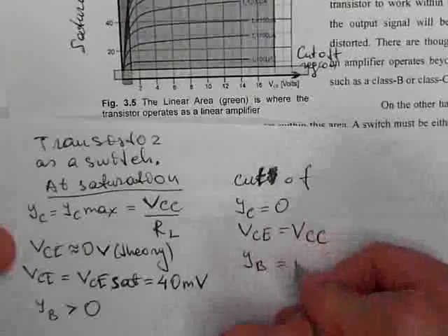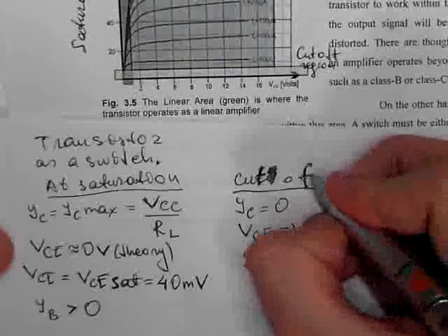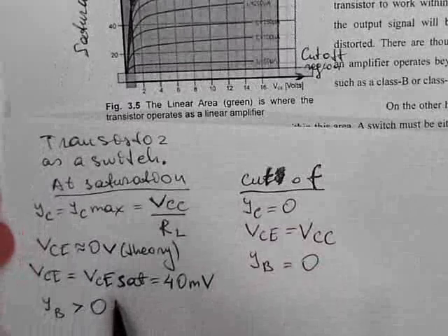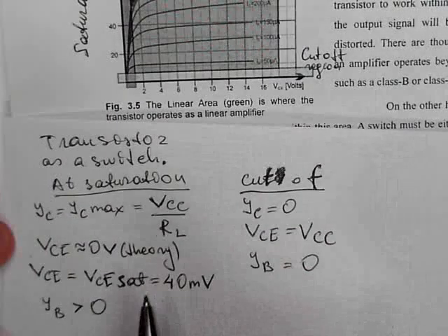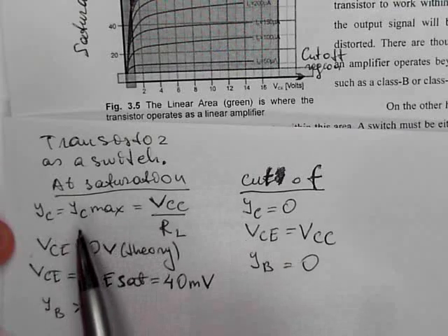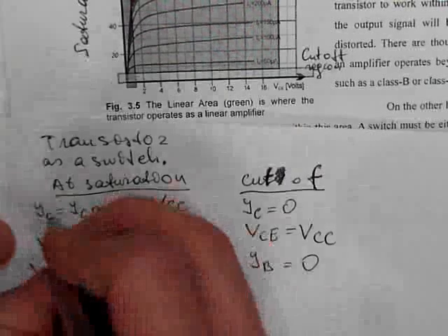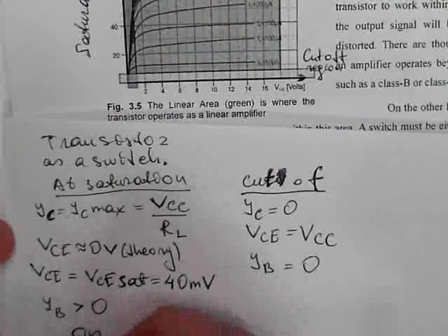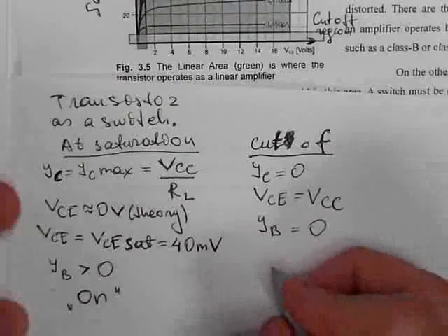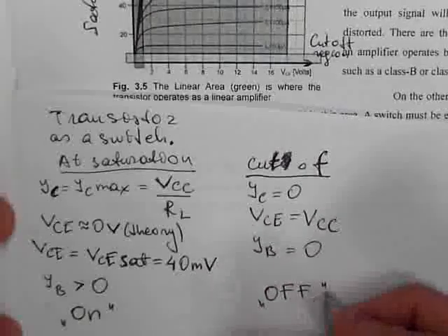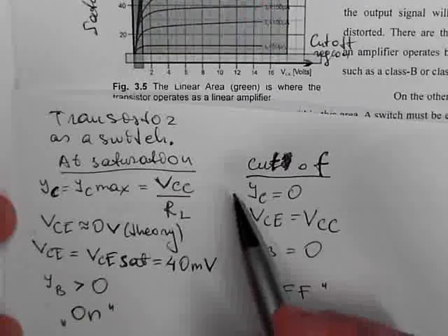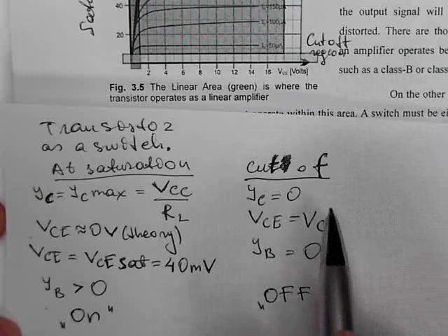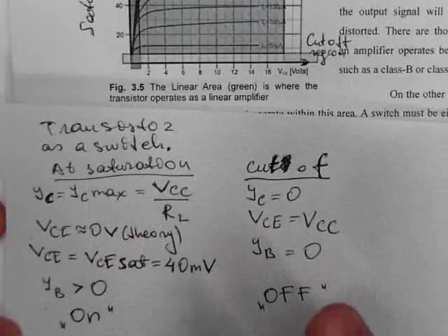So two situations. When using as a switch, the transistor has to be either fully on. So fully on it is here. We don't want any intermediate currents. So we need either the device working, when IC is max, so it is on. Here these are off conditions. The device is not working, no IC. So transistor operates between its fully on and fully off conditions. So between its border conditions, we can say. So what happens in these conditions?